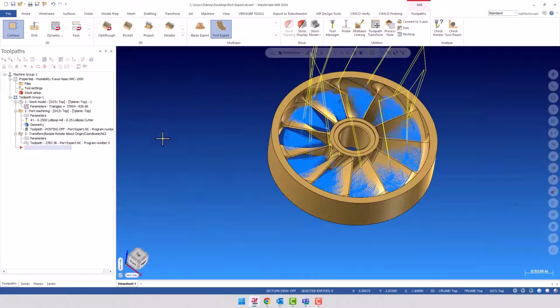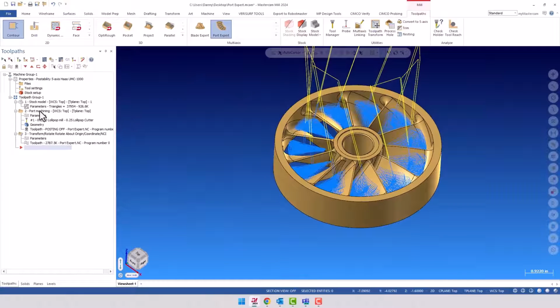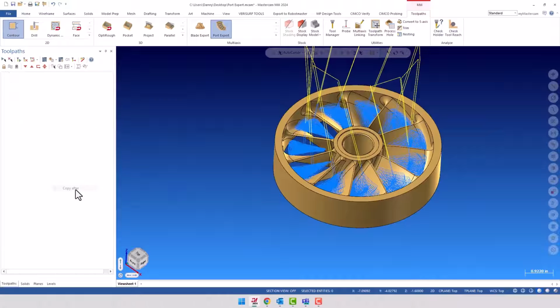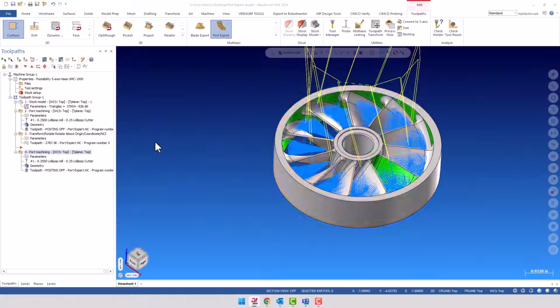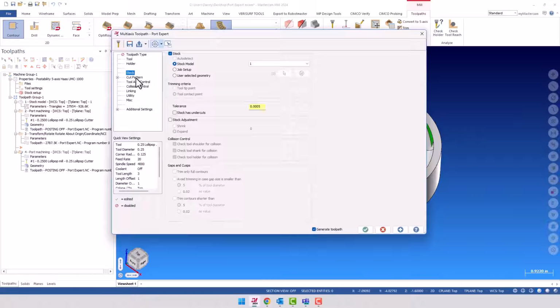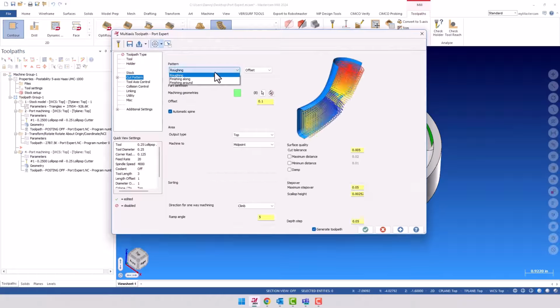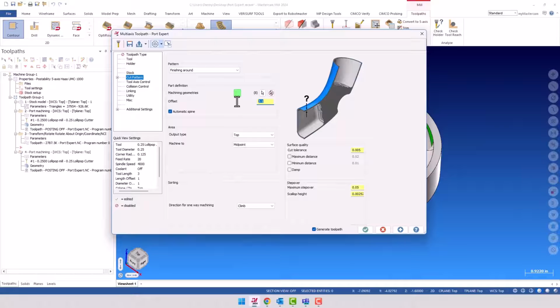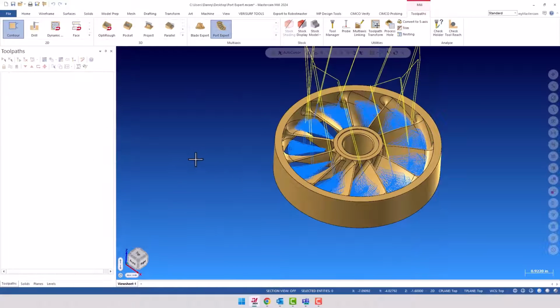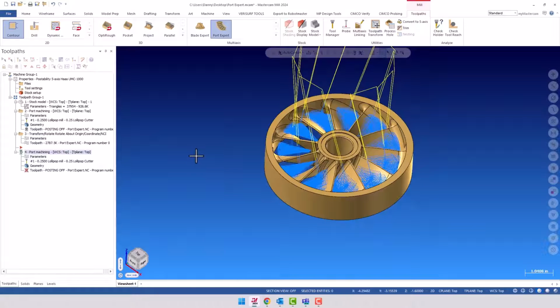And then actually I'm just going to take this toolpath. I'm going to copy it, or I'm going to be bold here, I'm just going to copy it afterwards. If we wanted to change the strategy to, say, a finish around, I'm going to still leave material in case we need to come back with a smaller tool. Let's say I leave 50 thousandths here, just have it take material off. I'm not going to change anything else. Just select OK to this and let it calculate that toolpath.